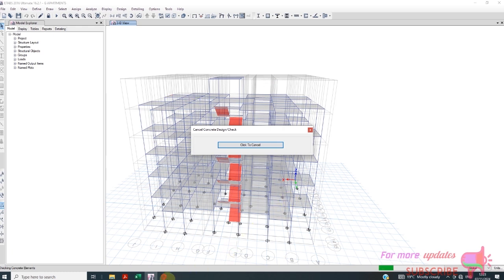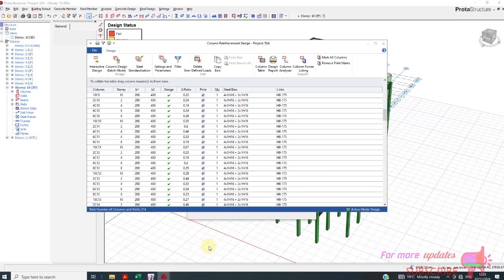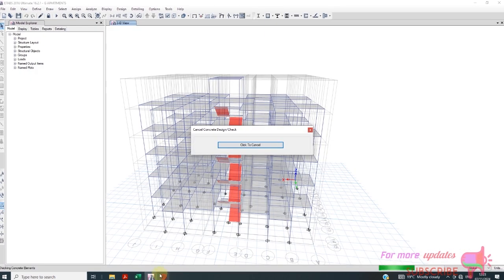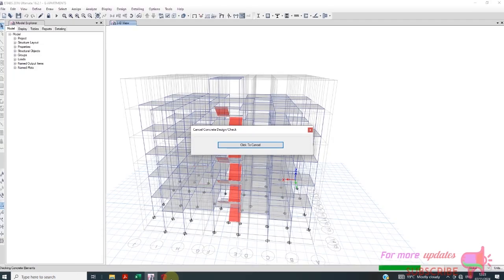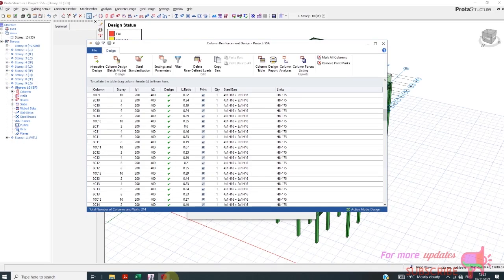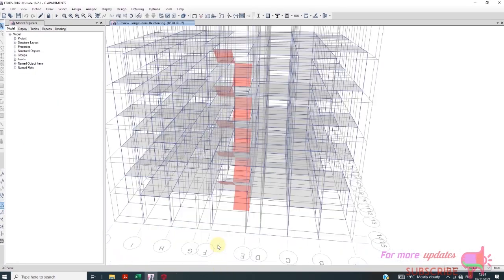Okay, this building is having walls, that is machine cut masonry wall. So I think the building is not sway structure because it is braced. As long as there are those walls, it means that the building is braced. So when you're designing the columns in CSI ETABS, it will not be sway structure, it will be just non-sway. Right?